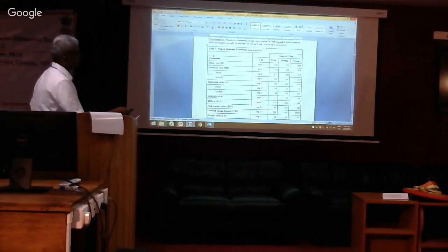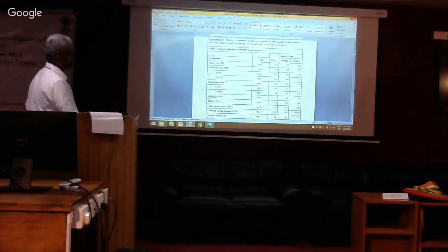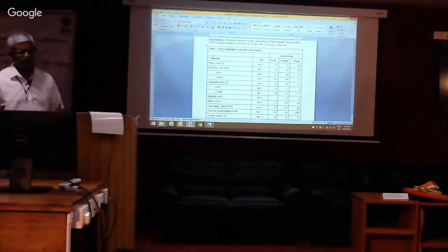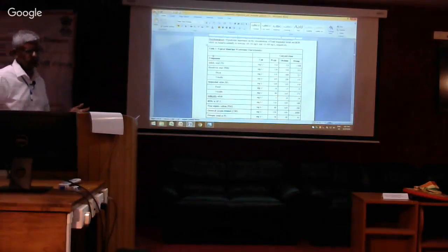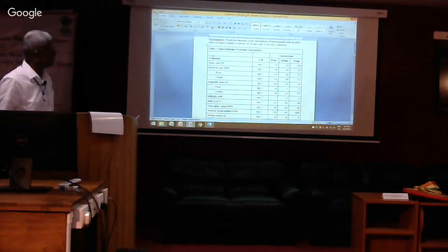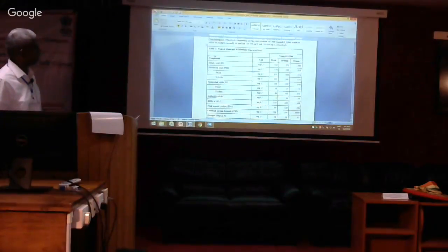You see there are 3 columns here, weak, medium, strong. We are looking at solids anywhere from 350 to 1200 milligrams per liter, out of which total dissolved solids, TDS, are 250 to 850. And these are just guidelines. These are not hard and fast numbers. I picked it up from the most widely used wastewater treatment plant design book, the one by Metcalf and Eddy.